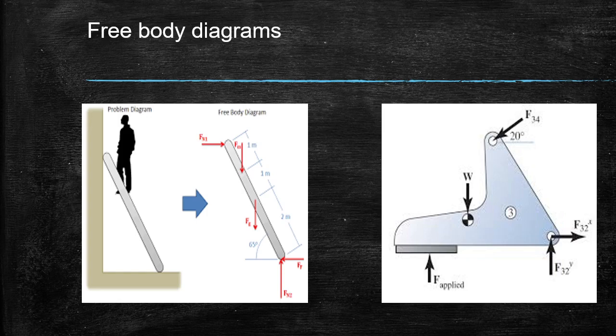Now the simple thing is the free body diagram. You have to draw a free body diagram. It looks simple, but if we neglect some of the forces, then the result might be devastating. So just focus on all the forces which are acting, which might be acting and which may act. If we draw a free body diagram in a good way, then I would say that 80% of your work will be done. So just draw and then calculate. Then next is just simple mathematics, 6th or 7th class mathematics.